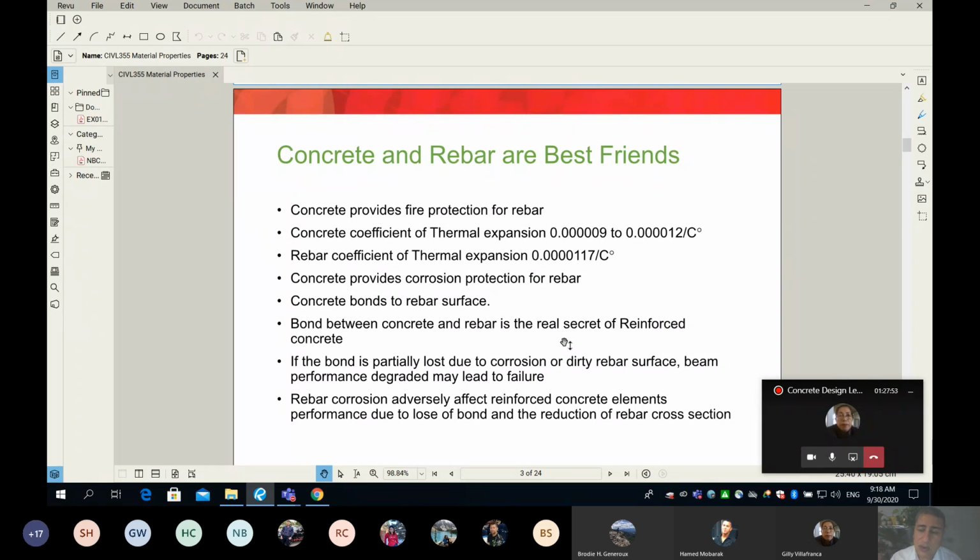So if you're doing an inspection and you look at the rebar and the rebar is not clean, what can you tell? What's any input? Anybody who's still awake? It won't bond as well. Thank you, sir. It's not going to bond as well. So if at some point in your life you're doing an inspection and you look at the rebar and it is not clean, meaning there is lots of debris and lots of dirt on the rebar, then ask for the rebar to be cleaned. Ask for cleaning the rebar because you know that the bond will not be the best, and bond is the secret.